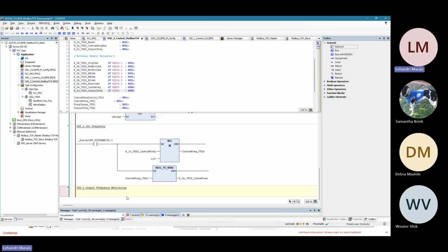All that has to be done for display purposes is scaling the value back to normal. So once again, when we read the frequency, it will be multiplied by 100. So to display it appropriately, you will be required to divide it by 100 to display it accurately.